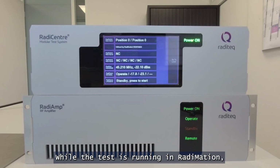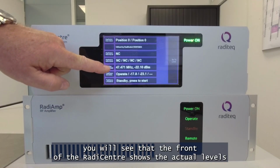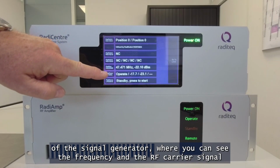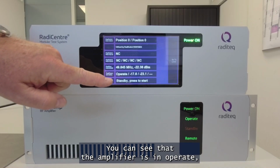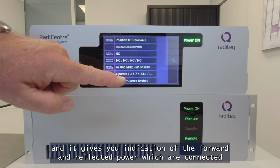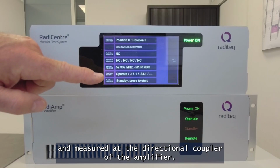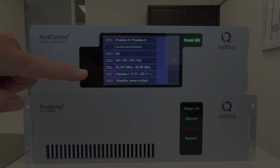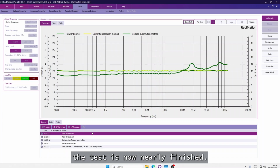While the test is running in Radimation, you will see that the front of the Radicenter shows the actual levels of the signal generator, where you can see the frequency and the RF carrier signal. Underneath, you can see that the amplifier is in operate, and it gives you indication of the forward and reflected power, which are connected and measured at the directional coupler of the amplifier. As you can see on the graph, the test is now nearly finished.